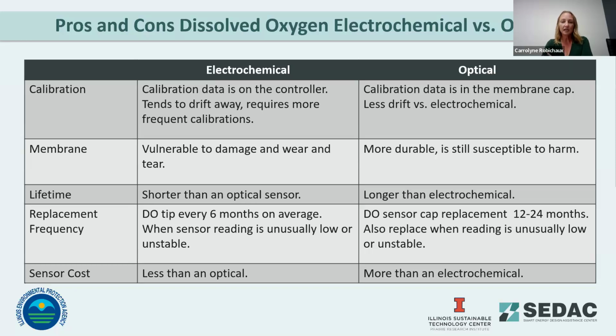One of the advantages to that is you can actually have a separate controller in the lab. You could do this for pH probes nowadays too. You can do any calibrations or verifications in the lab. You can remove that probe from process, take it to the lab, clean it up, calibrate it or verify it, and then you can alternate it out with another probe. So what does that give you? It gives you more steady, consistent calibrations. Instead of having multiple people doing these process calibrations, you can have one person.